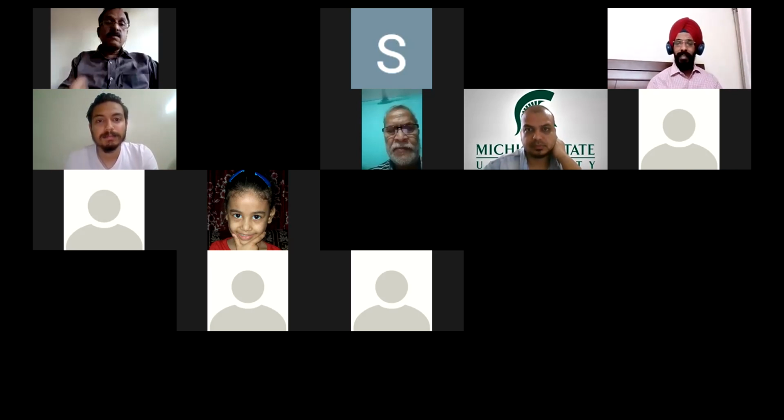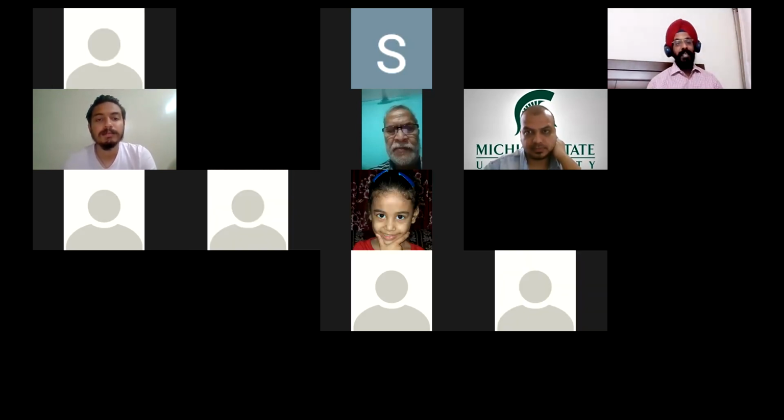Yes. And there is one more question, that I am creating shape files. Yes, we have to create shape files on our own. Most of the time we cannot get shape files freely. Although we can get some low resolution images freely, most of the time vector data or shape files we cannot get freely, so we have to create them. Of course, Indian road data is available on the net also, but we cannot rely on that data, maybe created around 8 or 10 years back. So if I want to do a good project, most of the time I have to create my own shapefile. Okay, I think you got your answer, right?